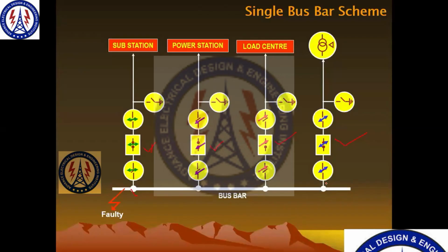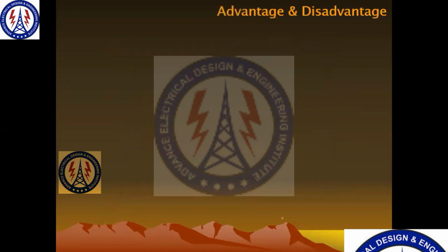There is no power supply the substation is dealing with at this particular moment due to the fault on this bus bar. Got it? So here you can see when we have a fault on a feeder, one feeder is interrupted. When you have a fault on the bus, all the feeders have power interruption. These are the two things. When you clear the fault, the system will again work in a healthy condition.